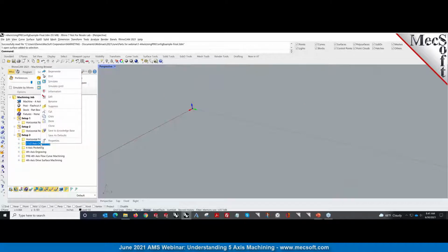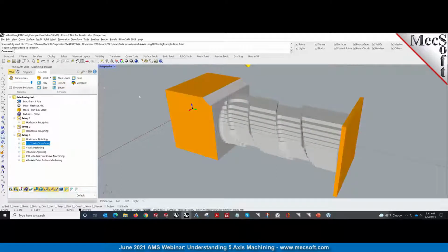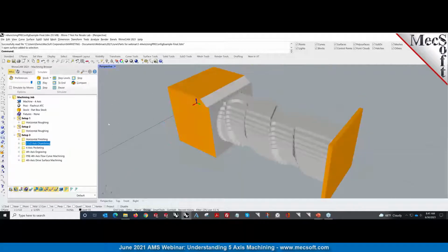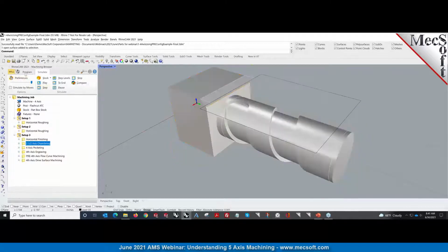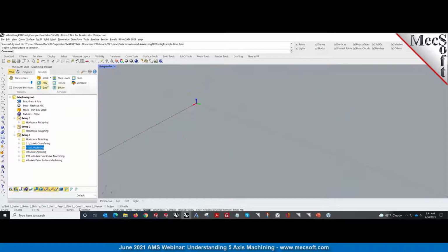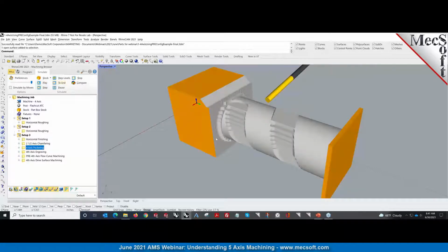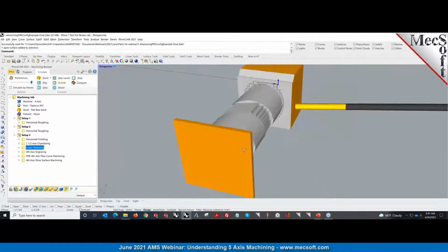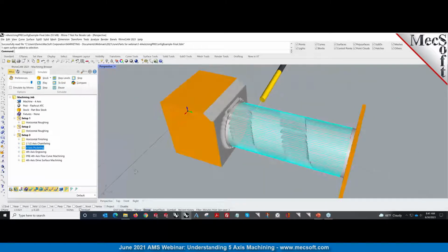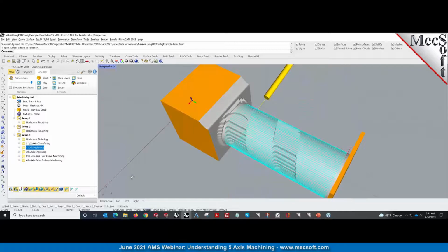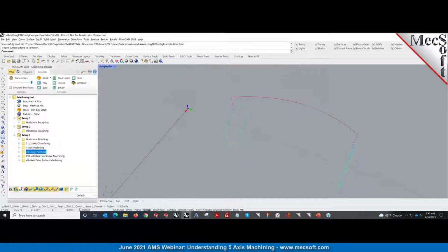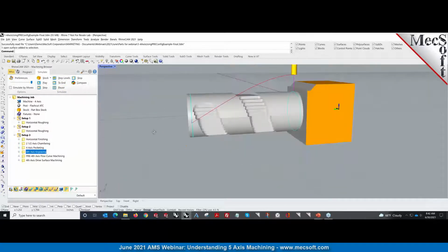And then we did a chamfer operation to remove that chamfer. So all of this is 3-axis methods. Until here, we have 3-axis methods. Now when we get to the rotary part, we're actually jumping into some 4-axis methods as well. So we're using quite a bit of combination. We just clean that up. Let me show you the toolpath. We use the 4-axis face-off operation, if you will, and then we also use the 4-axis engraving operation to clean up the sides to get it like that.